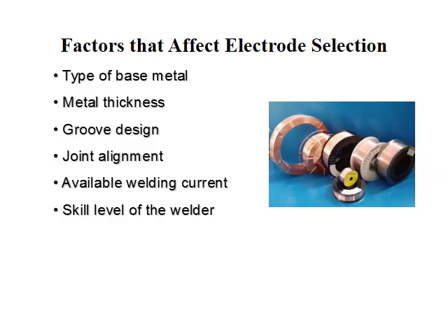If you come up to them and say, hey, just weld this, and the welding engineer asks the person who needs it welded, what is this? And the person needing it welded says, I don't know, just weld it. No, it doesn't work. You need to know what the base metal is before you start, or have a general idea. You might not need certified material test reports, but it's a good idea to know what you're welding on.